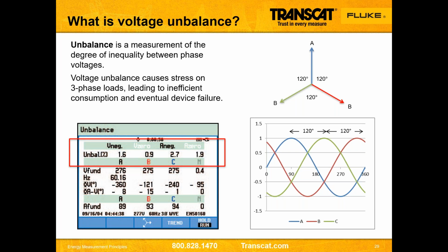For those folks in the audience who are using variable frequency drives, that unbalance cannot be more than 2 to 3% on a voltage. VFDs cannot compensate for unbalanced voltage, and as a result of that, unfortunately, we'll drop a voltage out to one or more phases to the motor, and the motor will pull more current, and the drive will trip. And we will all blame the drive, but the reality is it was not balanced going into the drive to begin with, and the drive could not compensate for that. So how do I know why the drive is tripping? We can use these types of tools to help figure that out as well.